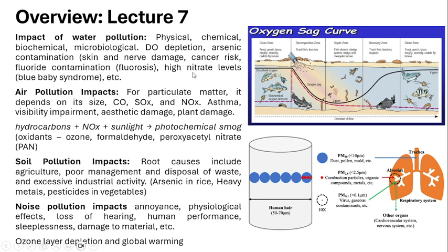When a higher level of nitrate enters the water bodies, it will cause a condition called methemoglobinemia. It attaches to our hemoglobin complex and causes suffocation in breathing, and it is also called blue baby syndrome.